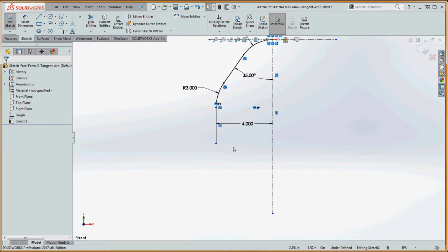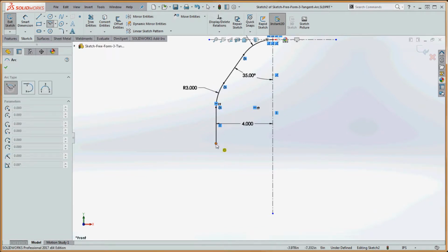And the next thing we want to do is put in an arc in here between that point and maybe somewhere out in space out here. And this gives me an opportunity to do the Centerpoint Arc. We're going to do the center point from this line over here, from the vertical center line that we have. And right now we're just floating our cursor around our graphics area. If we take our cursor and follow that over, not necessarily selecting it, but resting over that line, you can see a horizontal dashed line out here. If we were to pick up this vertical center line here, you can see we're going to get a coincident relationship on it. It's going to maintain that horizontal relationship over here too.